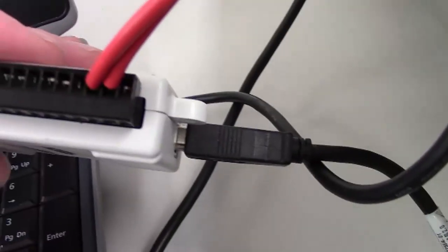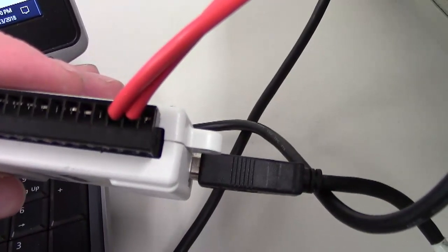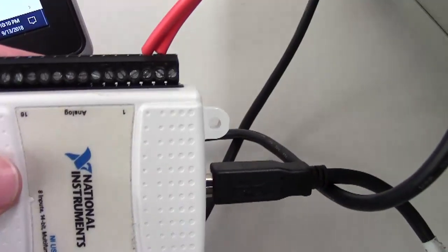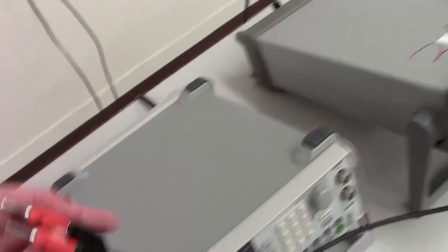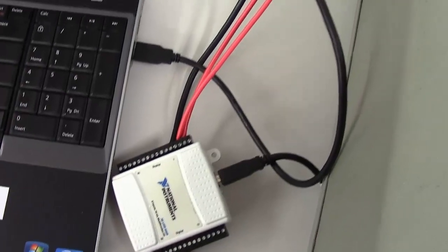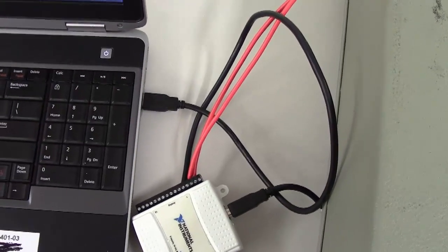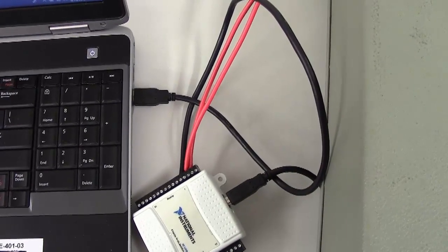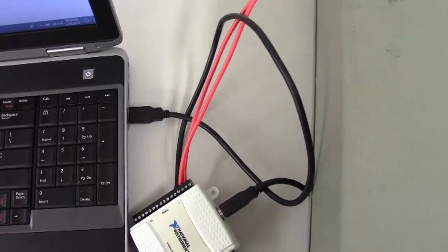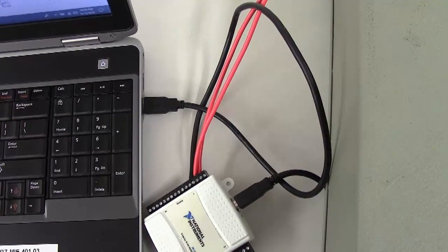But what I have here, so you're going to use a small screwdriver, you can see there. You'll want to open those up inside of there, twist your wire and put it in, and then screw it down tight. So this is a cable that has banana plugs on one end, and on the other end, those banana plugs have been cut off. We only want you to use the cables that have already had those banana plugs cut off. Don't go cutting off your own. We're going to need lots of those with banana plugs on both ends for future labs.